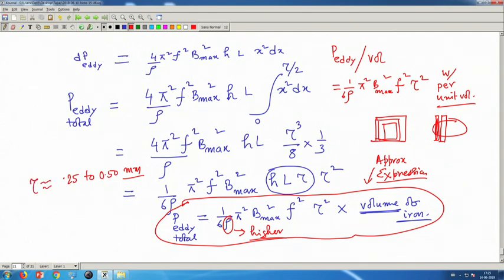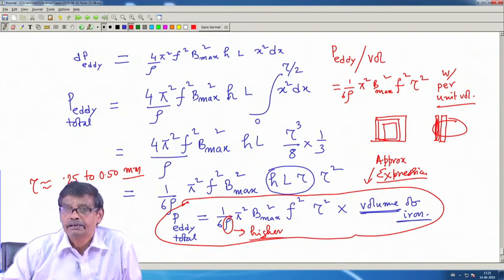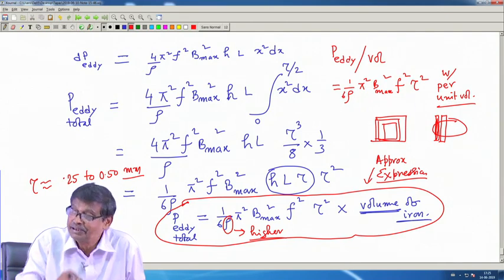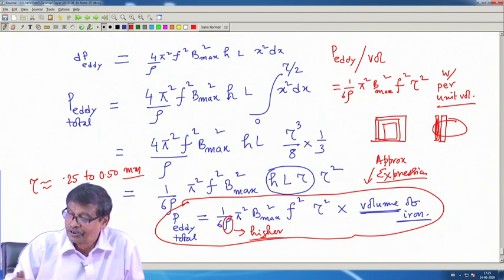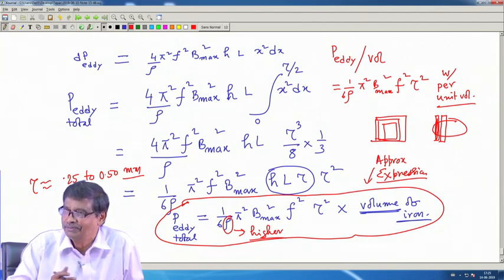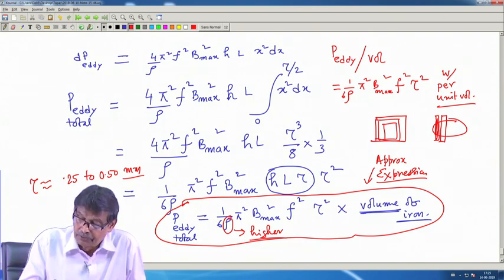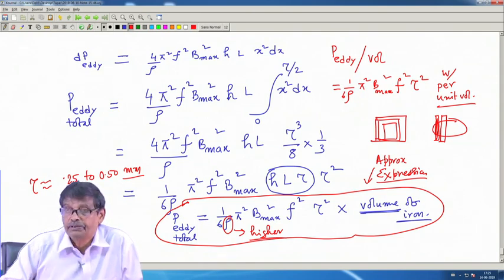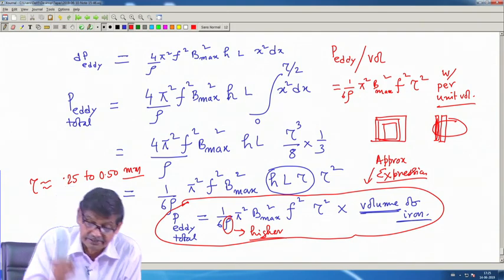And transformer size, if you see, they may be of the order of a distribution transformer. If you look at, their heights may be in meters. So, the assumption that H and del compared to tau is very small is pretty good. But do not use just iron, try to use a better material, that is why people use silicon steel.